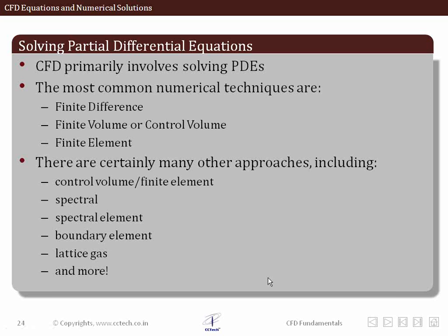Now partial differential equations also follow a similar philosophy for getting solved through methods like finite difference, finite volume, or finite element method, although there are a variety of other methods by which people have tried to solve the equations which govern the fluid flow, because they are most of the time partial differential equations. Now for such partial differential equations, these methods like finite difference, finite volume, and finite element all require one common thing, which is grid generation. That is, the space x and y dimensions, or z dimensions if it's a three-dimensional problem, has to be discretized.